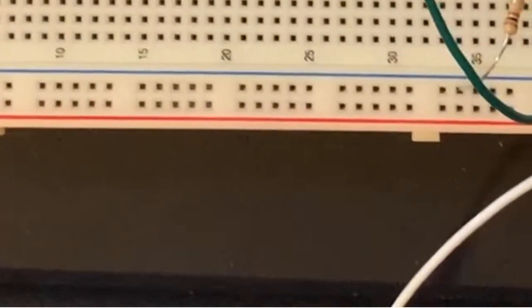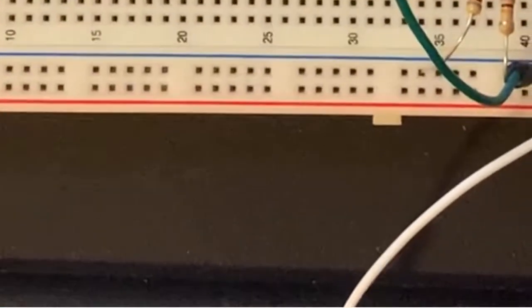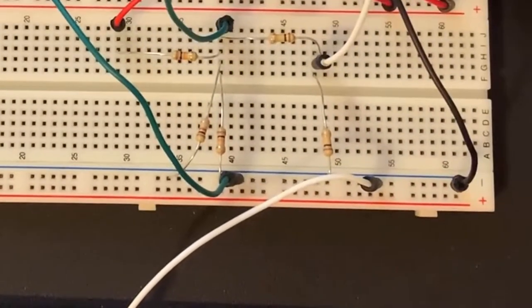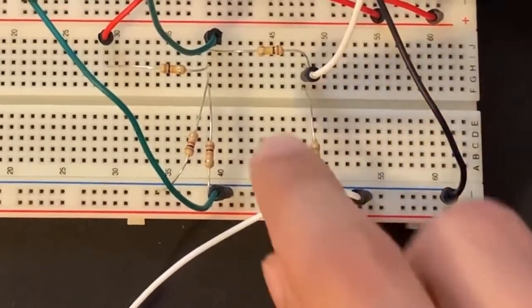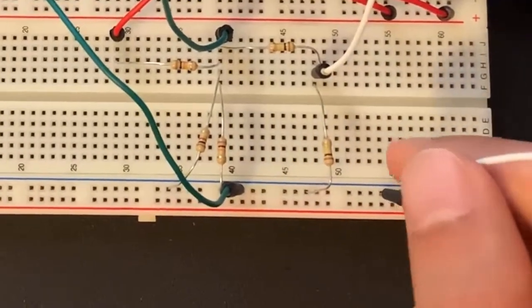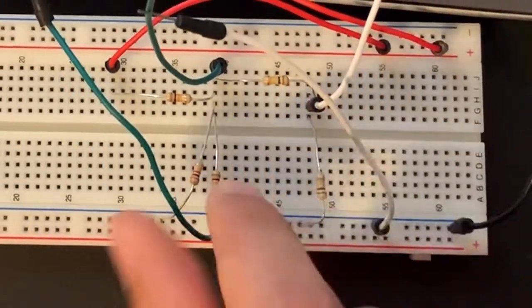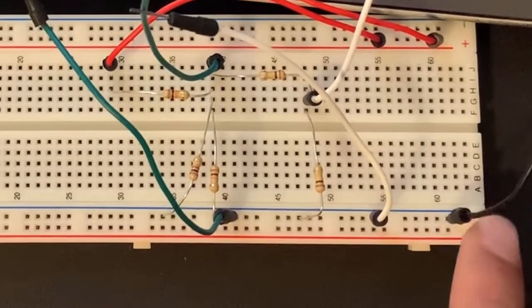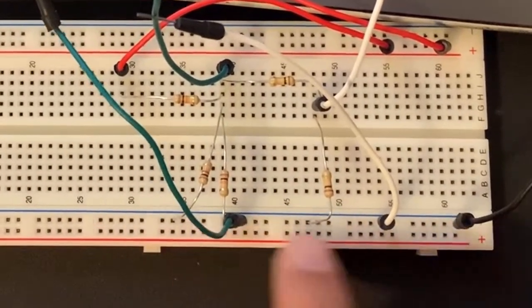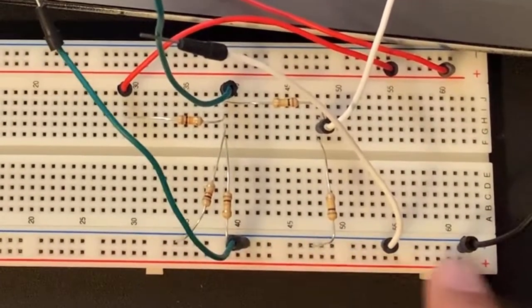As you know, we should use two wires to measure each voltage referred to the ground. So I'm using another white wire and another blue wire, and both are connected to the common ground. All these points have the same voltage, which is the ground voltage.